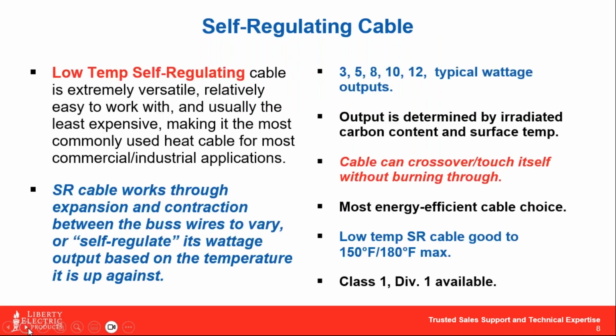Now, self-regulating cables. Low temp self-reg cable is what you're going to see predominantly in a lot of these scenarios because it's so versatile. This cable has a great temperature range that it can work within, and there's no question it's the most energy efficient. It's also the one cable that can touch against itself without destroying itself, and that alone makes it the most popular cable choice.